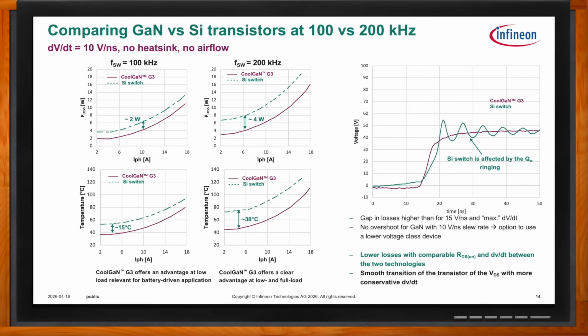The green is silicon, and you can see it starts out with kind of a slope at around 10 nanoseconds. You can see it's starting to rise. You might be wondering what's going on there. That's reverse recovery, right? So what you're seeing here is that in that range around 10 nanoseconds where the GaN is still essentially zero or even slightly below, the silicon is already in this recovery where the high side's trying to turn on and it's fighting the recovery of the diode.